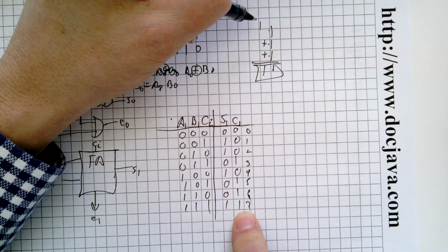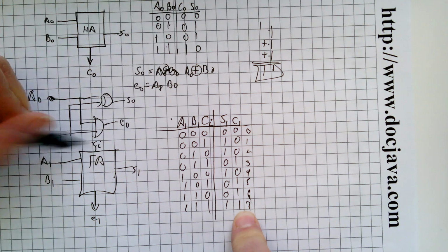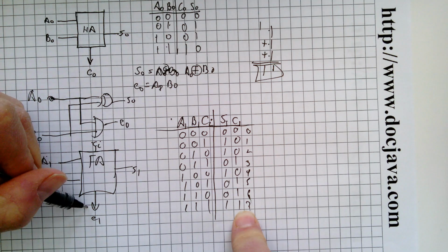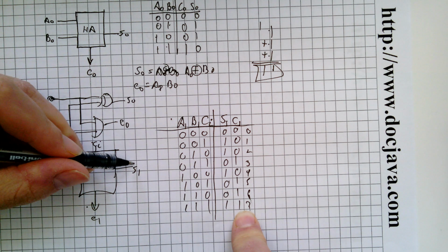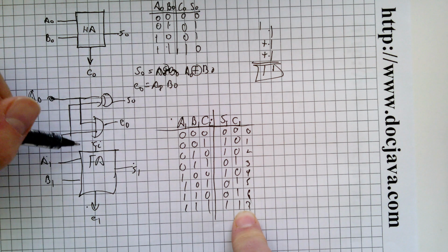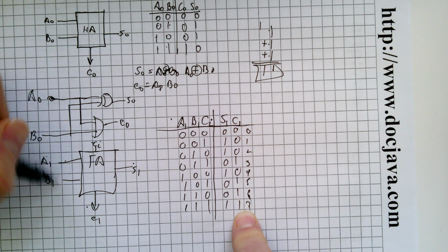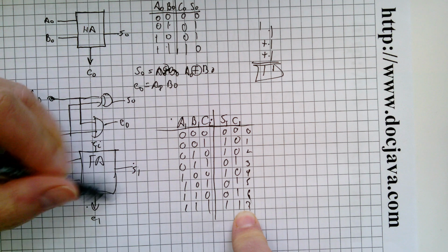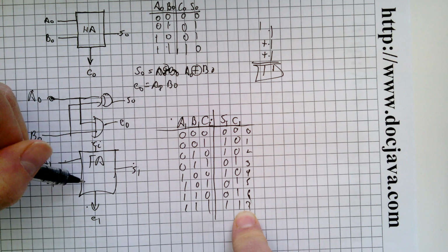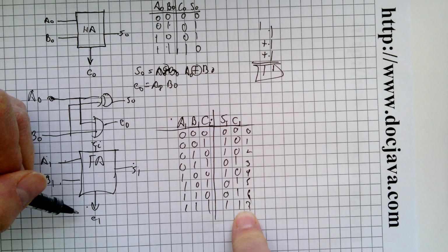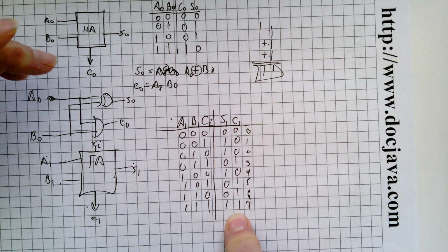When you have carry in and 2 1s, the output has to be a 1 for carry out and a summation of 1. Why? Because 1, 2, 3. There's 3 coming in, and so the binary for 3 bits coming in as 1 is 1, 1, which represents the sum of 3 bits.